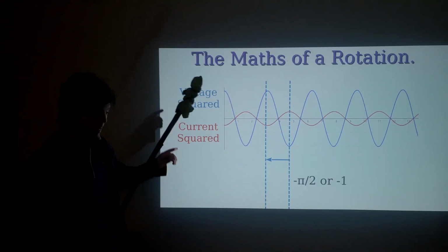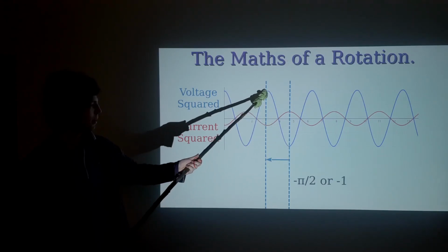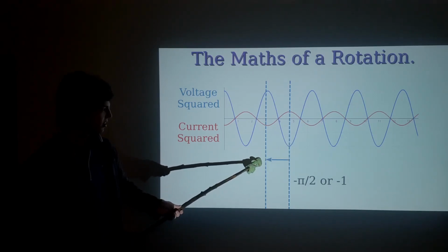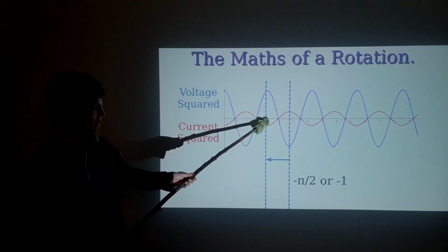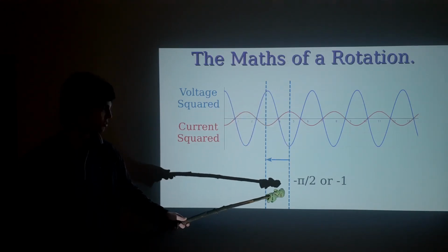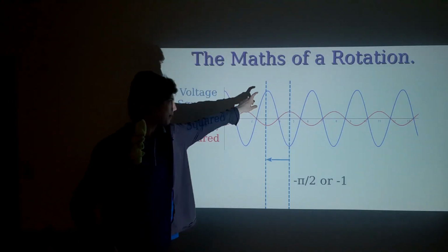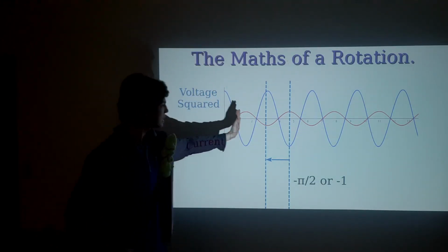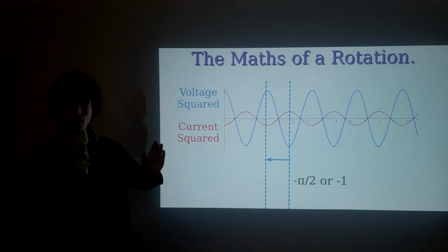Right, so that's not so tricky, but now there's a very interesting thing that happens. We can see that if we want to flip from the up to the down here, we only need to move half as far. So this is half of the distance. It's pi on 2 instead of a full pi rotation that flips our squared signal from the up to the down. But the pi on 2 still corresponds to a -1 flip, right? It's going all the way up here to all the way down here. That's a -1 multiplication to flip that. But the actual distance, the actual angle it's gone through here on the squared signal is only pi on 2.